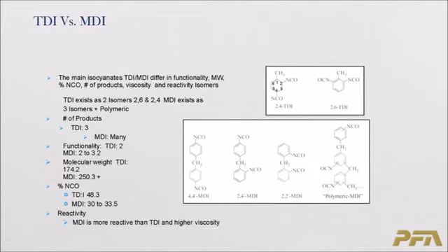That means if you're going to make a foam and you want to do the same index, MDI versus TDI, on a weight basis, you need to use more MDI in that foam formulation. And lastly, the MDI is typically more reactive than TDI is in foam formation.